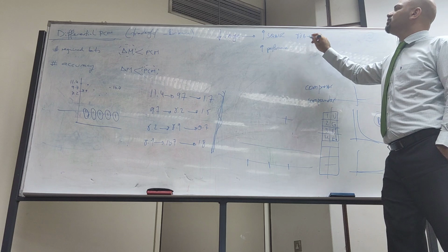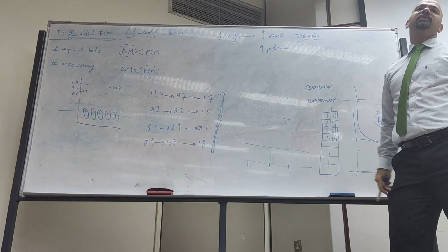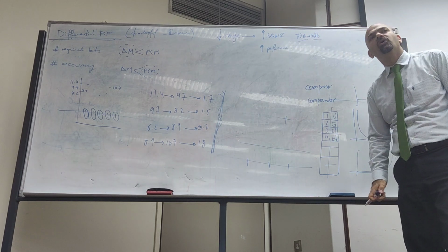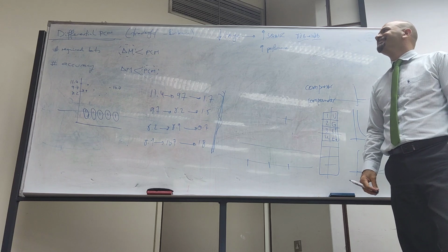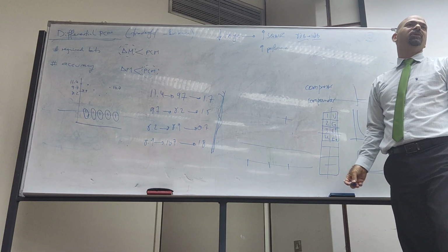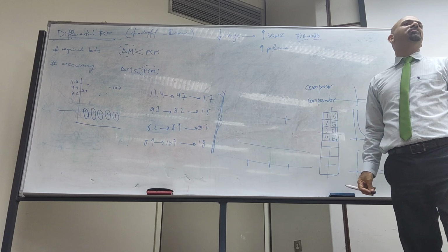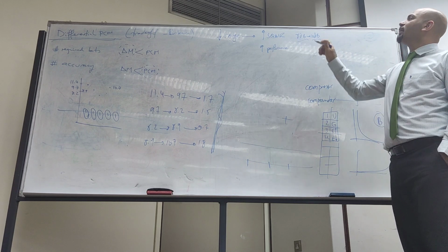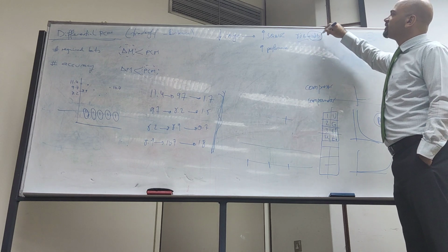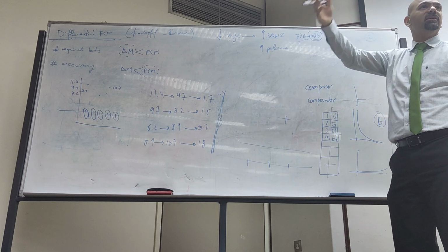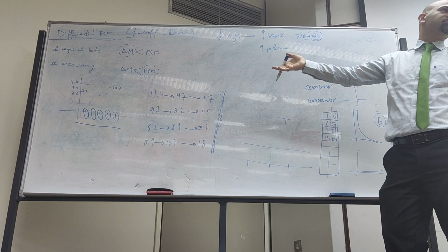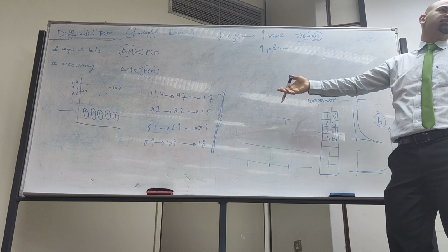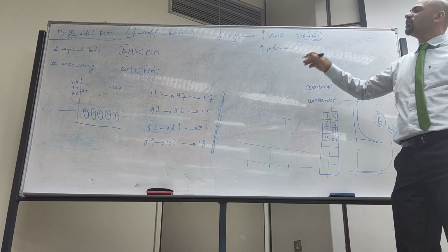Whenever you have 10 dB because of this, but you need only 8 dB, what will you do? You already decreased the range. For the SQNR, what are the other parameters that are in play? Bits. So here, this is your improvement, but you can invest it into fewer bits or less transmit power. Good?